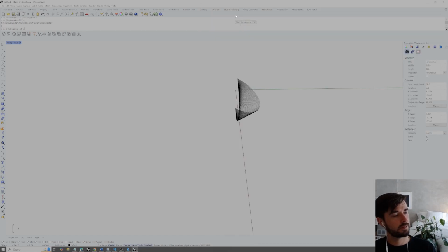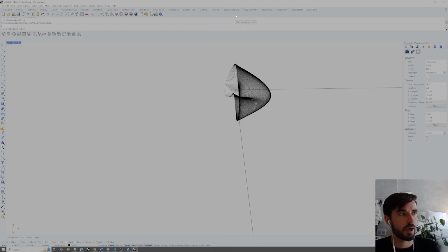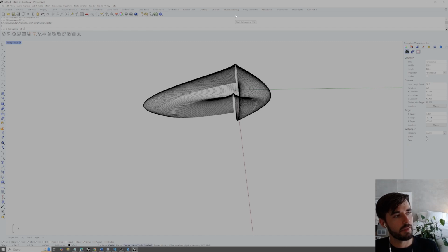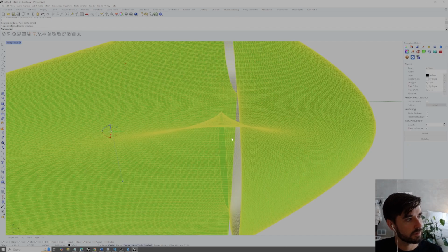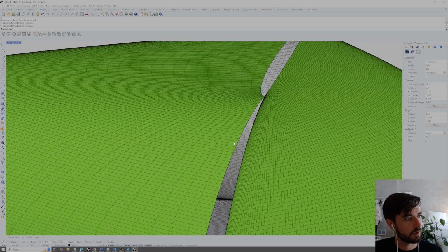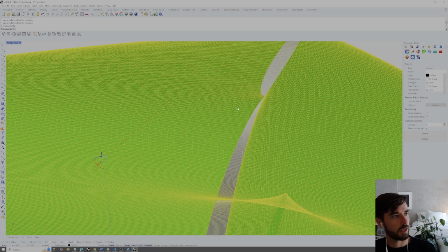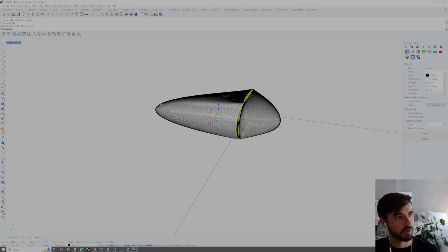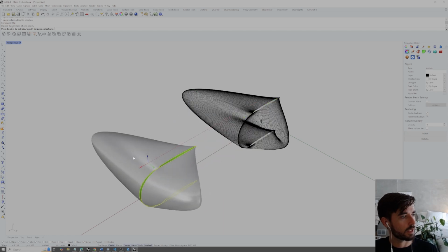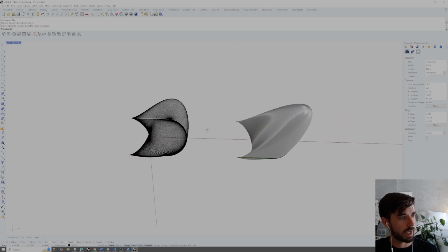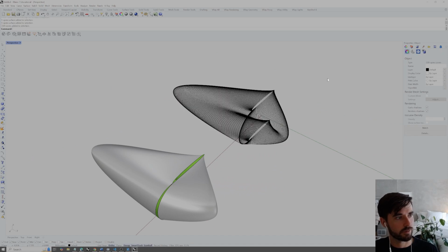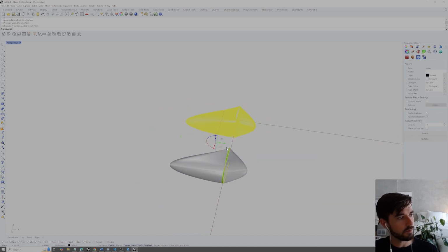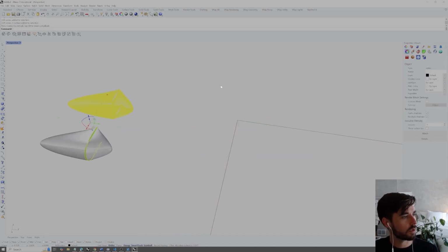Now when I hit play, it's going to draw out all of those curves, and then it's going to finish by constructing a surface, which we've done there. And we can flip this, turn off the ISOs, drag it out, and we now see that surface drawn out inside of Rhino. Then we still have the curves as well. I'm going to just go ahead and move this over.